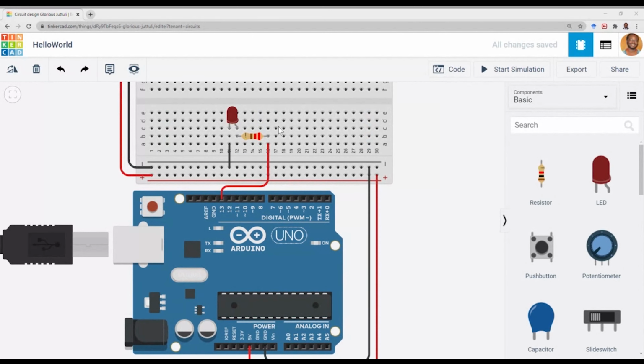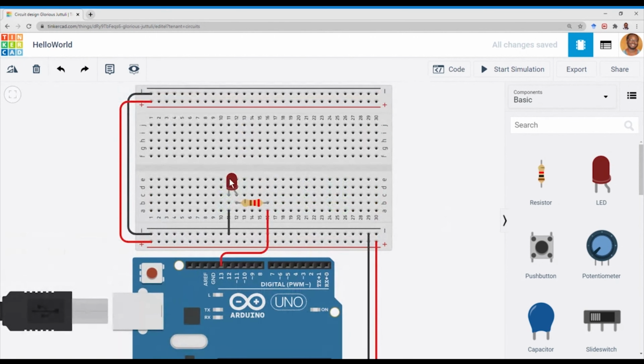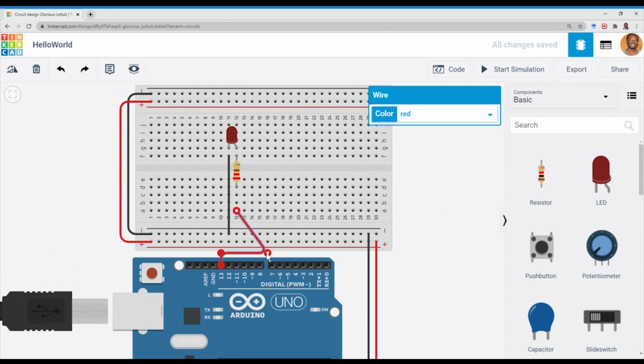Welcome back to the main screen. I'm on Tinkercad. Just want to clean the interface a little bit so we can write our own code. From the previous application, to rotate the resistor you press R, and you can drag and drop it to save space. To create another LED, just do Control-C, Control-V. I want to change the color of the LED by pulling the drop-down and changing it to yellow. Copy the resistor, and then set the resistor value there.